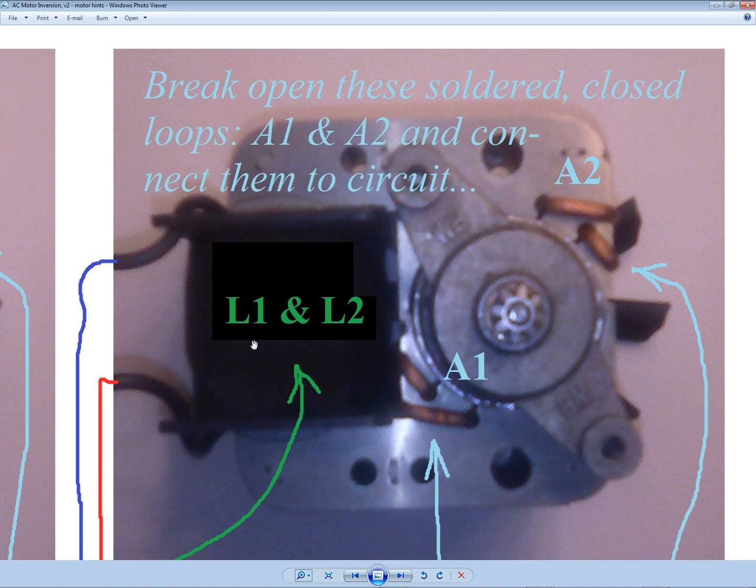So a unifilar is not the most efficient, and anything higher than a bifilar is also not very efficient. The magical number is 2. 2 windings wired in parallel.